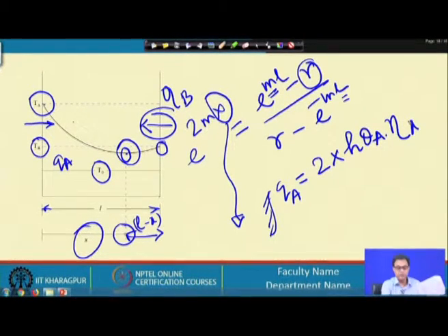As we have told that there is an extremum at this point, that means there is an adiabatic plane at this point. So, we know that we have an adiabatic plane at this point. So, which is the fin tip? The fin tip is at distance location x, and what is the temperature difference up to this point? Theta a.